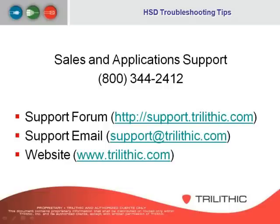Can you set the meter to record levels between a certain time frame? Now, I'm assuming this is talking about being able to start the meter at one time, record levels, and then set it to measure levels again. Yes, you can by using the auto test. You can set up auto test macros, and it will allow you to set a specific time or time frame and the duration of a test. You can set that with your auto test macros.